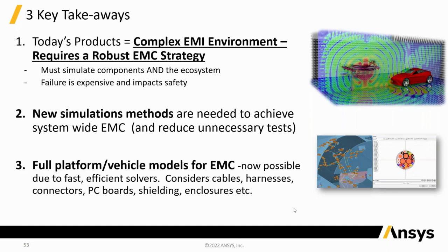So you could expect that it would take a little longer if you didn't have that many cores available. But if you get a 20 core computer that has fast processors, you could probably match that time. This 72 core one actually has pretty old processors, so that slowed it down somewhat. So it just kind of depends on what your use case is, how big your models are going to be, how complex everything with the harnesses are. But in general, the setup that you need is actually not that expensive. It can get expensive if you really want to speed up the simulation time, but to just get started, you could do it on almost any new laptop.